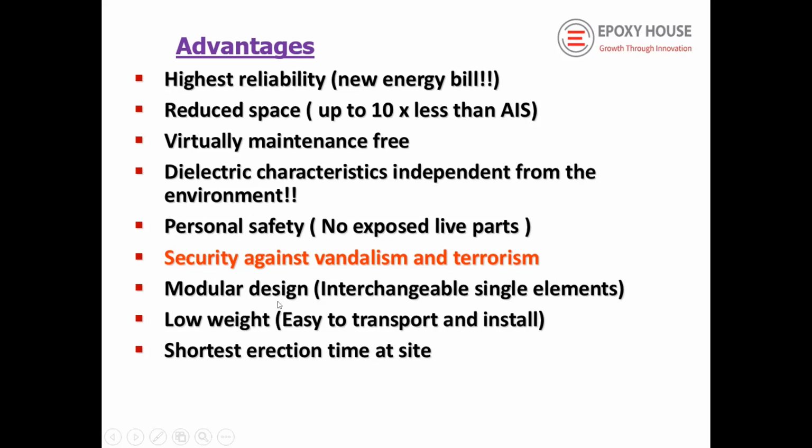The modular design means some components can be interchangeable, because one spare component can be used in any of the bays. It has a low weight compared to AIS because it's a very small space, so it is low weight. Shortest erection time, because it's pre-assembled in the factory. It has the shortest erection time at site.